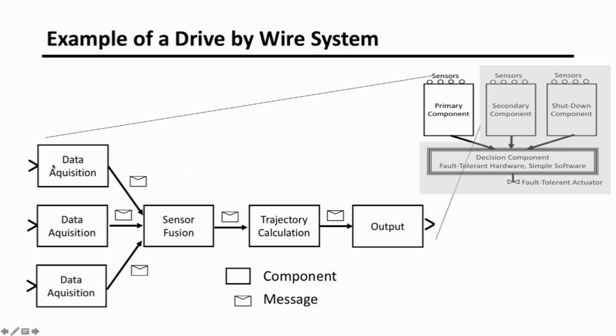And the value, remember yesterday we talked about the modeling relation. And we said that there's an algorithm that calculates out of the inputs the outputs in a time-independent way, just knowing for what time in the future it must calculate the outputs. And this is exactly the case here, that we have given time intervals, we call it the service intervals. We do time-triggered communication. There is no extra delay in the communication, just a minimal delay. Everything is synchronized, and we can come within the given time constraint from this point to this point.